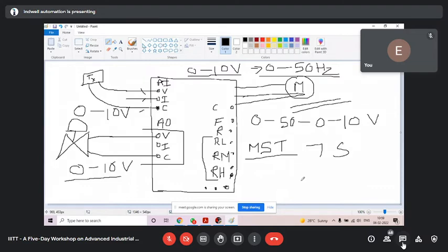See, you will say that, okay, I have to reduce the speed of motor, I shall take a gearbox, I won't use AC drive. But do you know, we have many applications where our motor should run on 75 hertz, it should run on 150 hertz, it should run on 200 hertz.